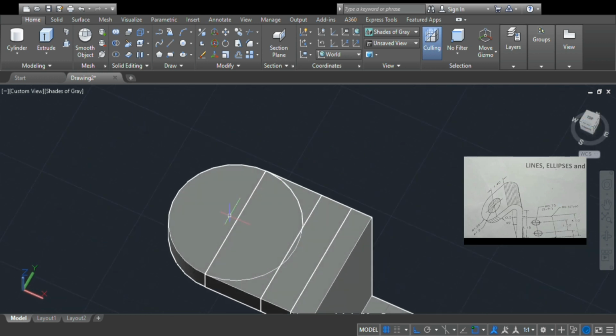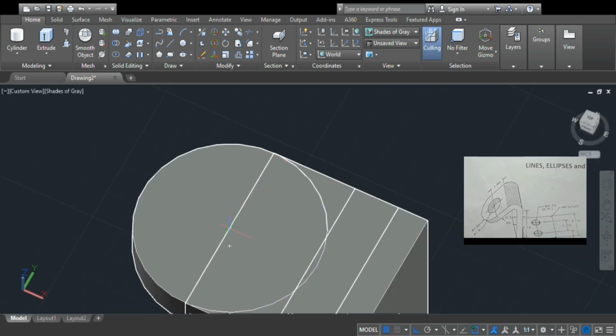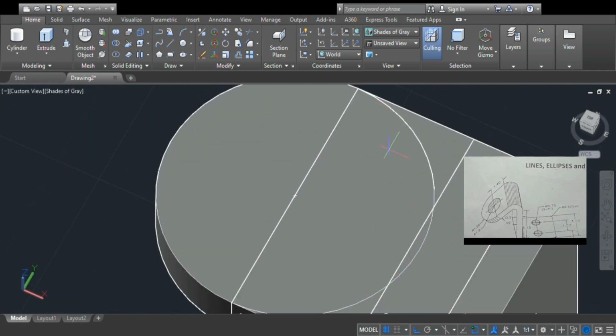Okay, the same thing you're going to do to make a hole here. To see the middle point of this circle, all you have to do, just like in SolidWorks, is move your cursor to the circumference of the circle. Then you click the circle, then you give it a radius. The circumference is 7.5, I'm seeing, so 7.5 divided by 2, I think, gives you the radius of the circle.